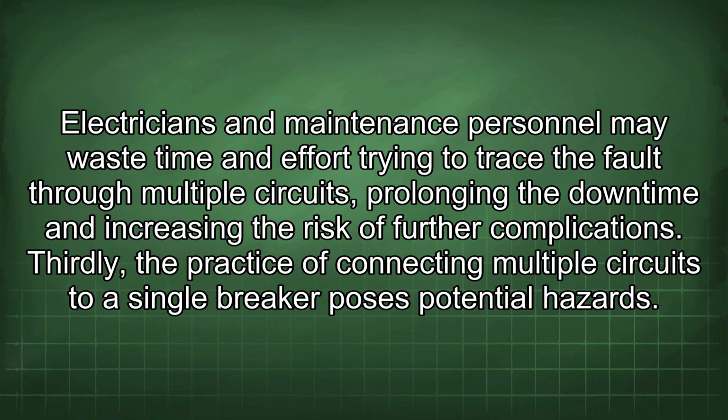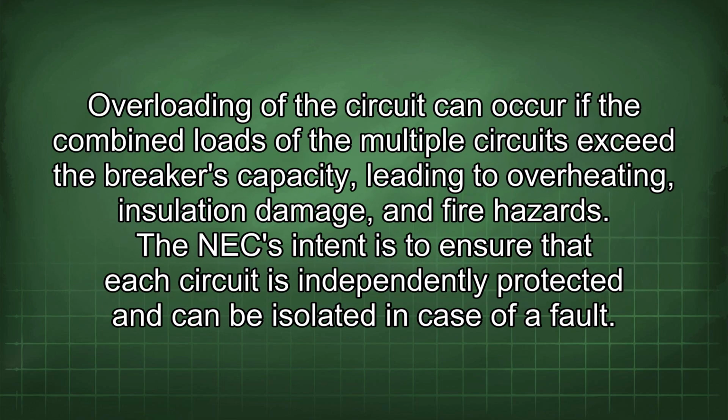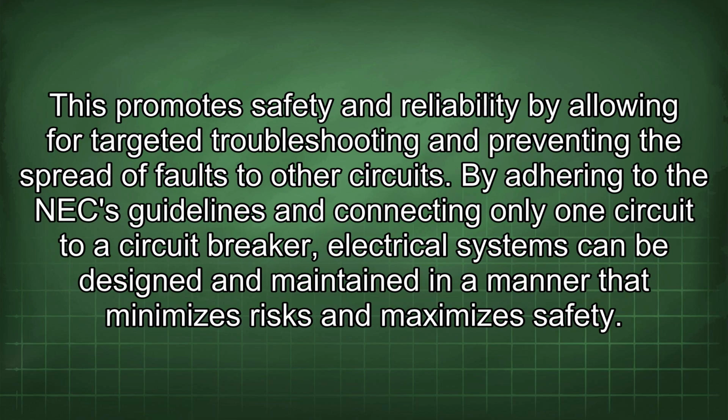Thirdly, the practice of connecting multiple circuits to a single breaker poses potential hazards. Overloading of the circuit can occur if the combined loads of the multiple circuits exceed the breaker's capacity, leading to overheating, insulation damage, and fire hazards. The NEC intent is to ensure that each circuit is independently protected and can be isolated in case of a fault. This promotes safety and reliability by allowing for targeted troubleshooting and preventing the spread of faults to other circuits.